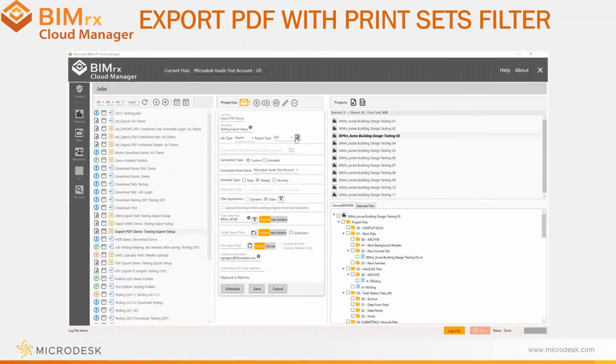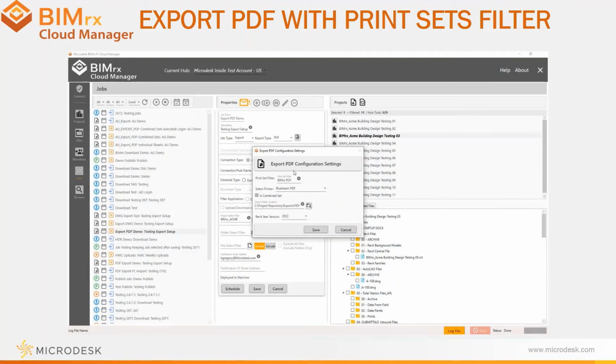I've created an Export PDF job, and we can find the Print Set filter in the PDF export settings. A Revit Print Set filter now enables control over which print sets are exported across multiple models and projects at the same time. If a print set name contains what I put in the filter here, it will be included in the export job. Next, I select the printer, Bluebeam if you have it, or a free PDF printer option is also provided. I can choose if the PDFs are printed as individual sheets or if they should be combined into one file per print set.